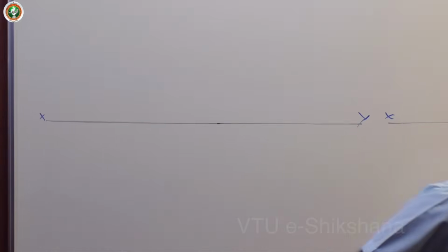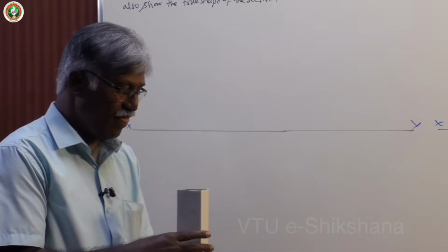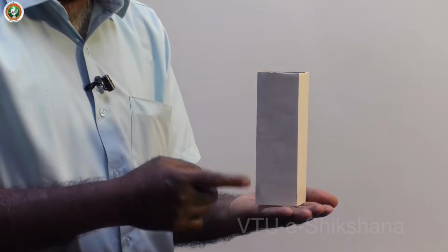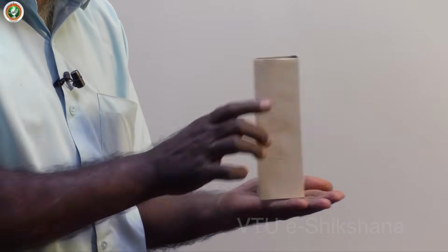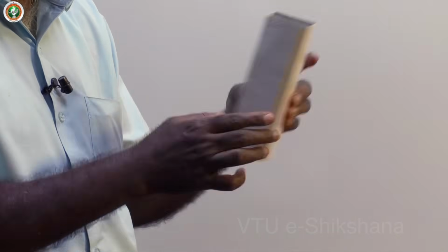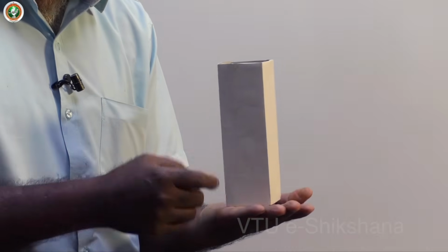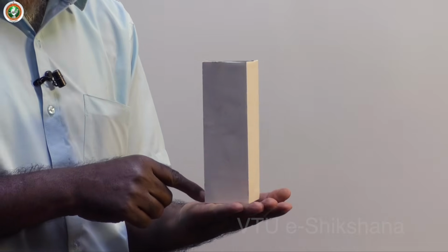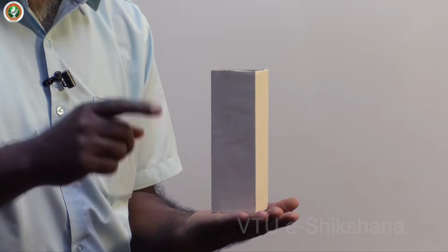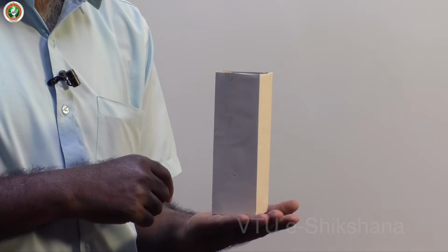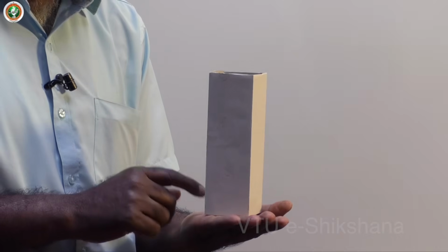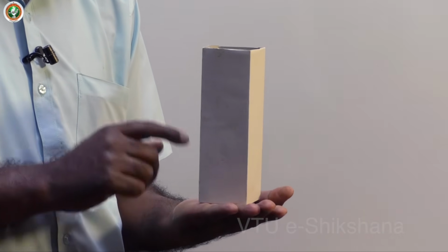If I take up the simple prism, this one, this is a square prism. Two base sides are parallel, that means number 1, number 2, these two base sides are parallel to VP, and two more base sides are perpendicular to VP. If I say a base side is perpendicular to VP, same position. If I say a base side is parallel to VP, the same position will work for that also, unlike the rectangular prism, because in the rectangular prism we have two types of sides. Here this particular orientation works for both the questions.